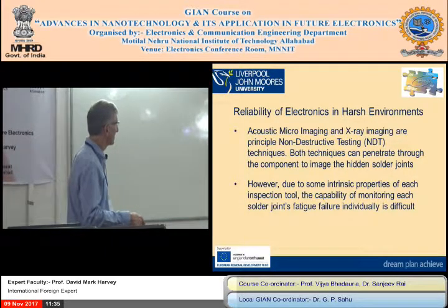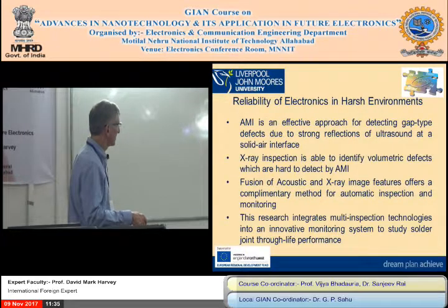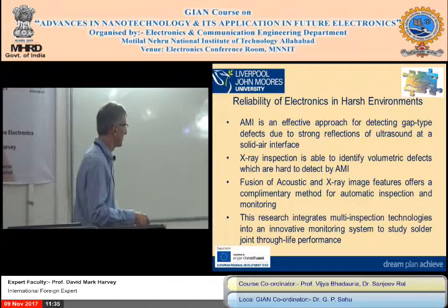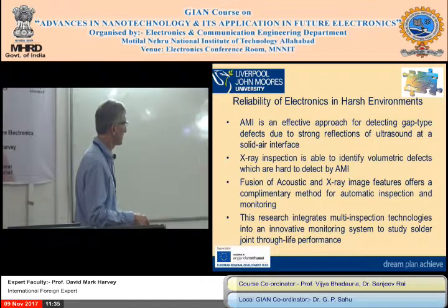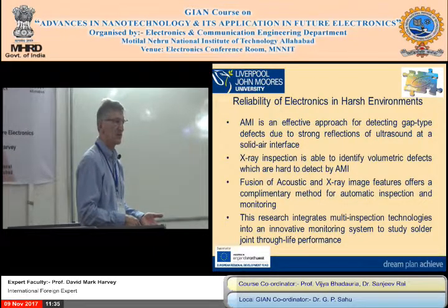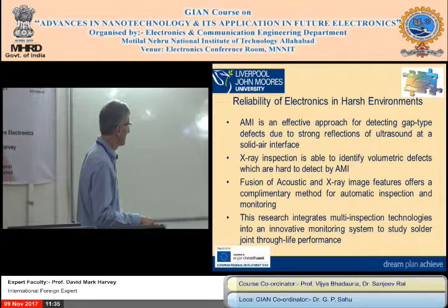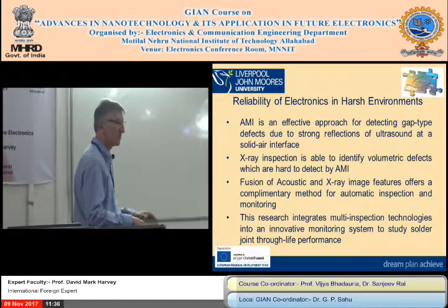So just a quick one. This is from a manufacturer data sheet, just so you know how ultrasound works. You have a pulsar there, sending ultrasound down. In our system, it's from about 5 or 10 megahertz up to 400 megahertz. So we need water to couple it. When we're doing the sensing, the circuit's not live, but it doesn't need to be. So it penetrates through the water, and every time it sees an acoustic difference between water and the chip, you get a reflection which we pick up in the same sensor. So we call it the main bang there, the first surface, the second, the third, you go down, but after a while it won't penetrate any deeper.